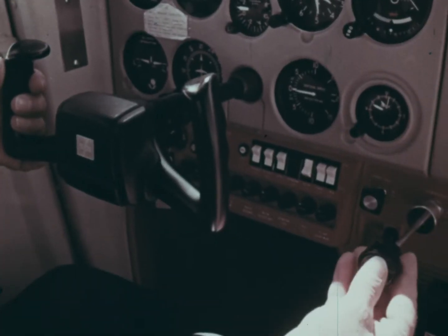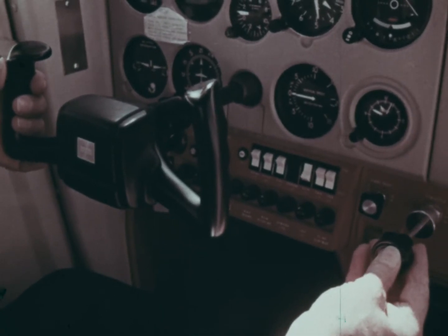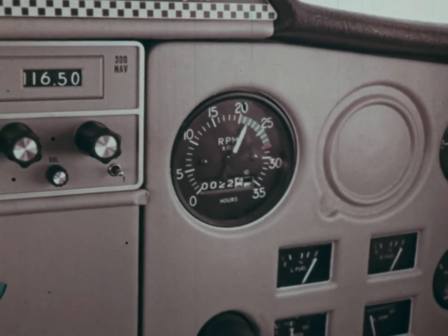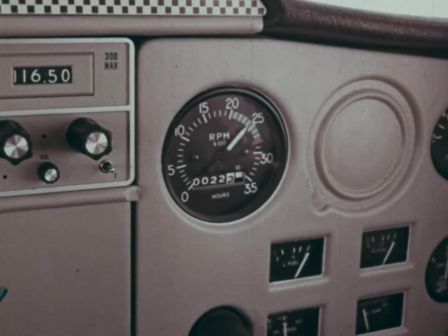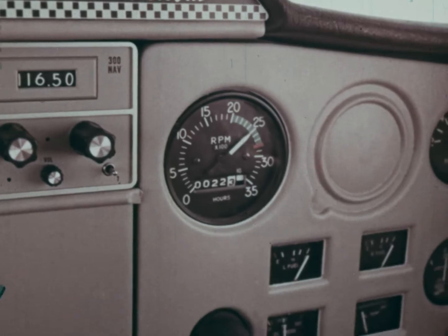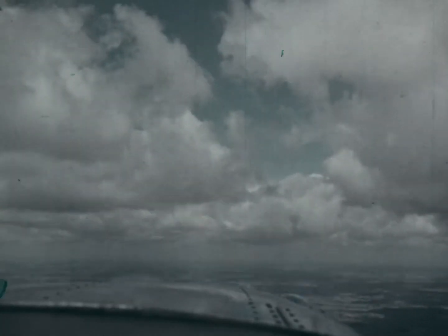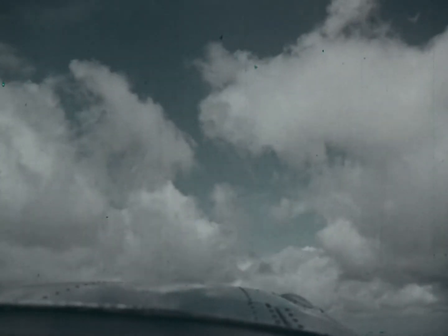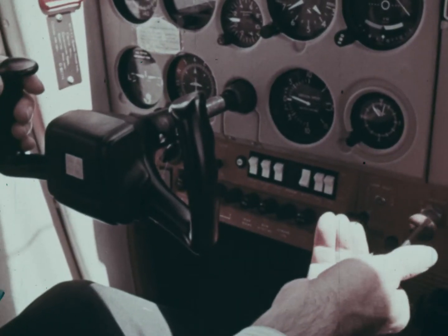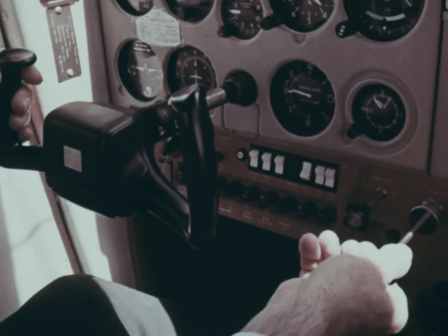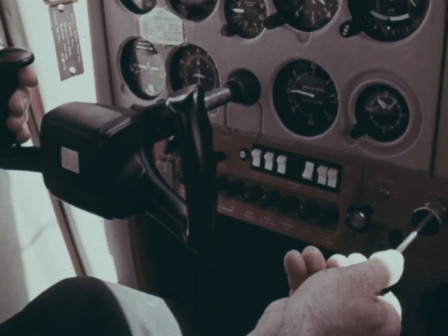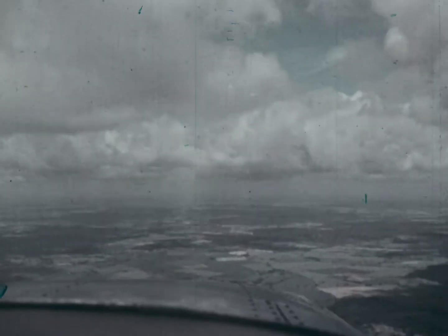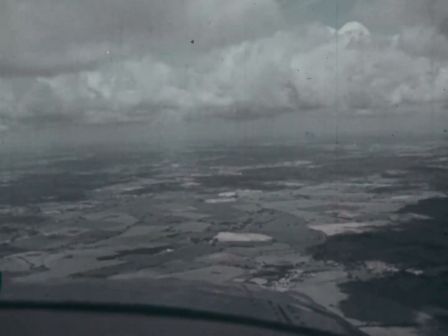And so, when we want to climb, we have to offset the effect of weight acting partly backward down the flight path by increasing thrust, just as we have to pedal harder to ride a bicycle up a hill. When we want to descend without increasing speed, we have to offset the effect of weight acting forward along the flight path and decrease thrust, just as we have to on a bicycle going downhill.